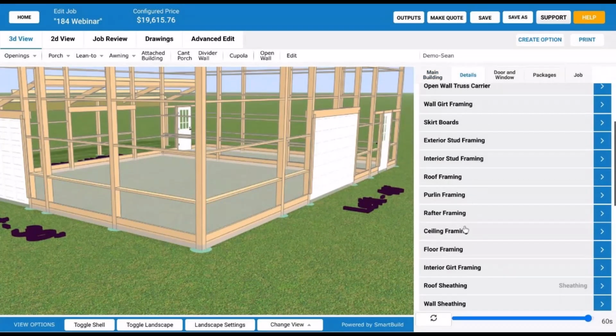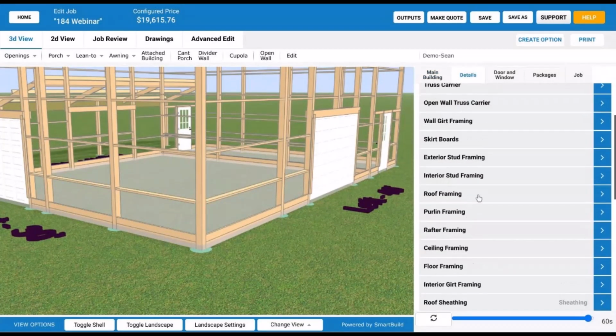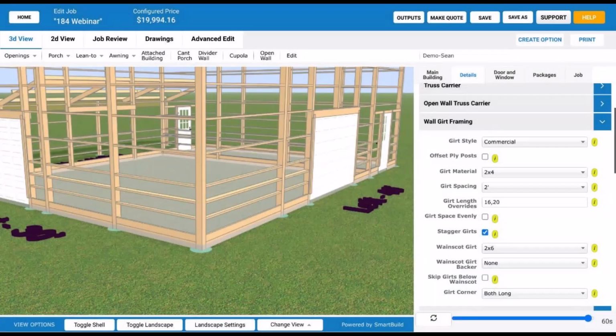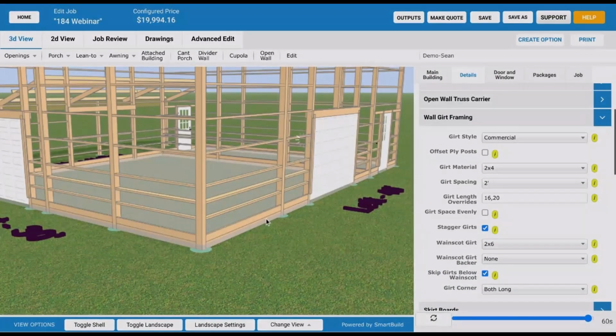Okay. Trent, would you actually set the skirt boards, or would you have a different girt? Because I would think you'd still want to use a pressure treated skirt board, but you wouldn't necessarily need to use pressure treated material up 4 or 5 feet. Unless they're wanting it to get wet, like if it's a calving barn, maybe they rinse it out.